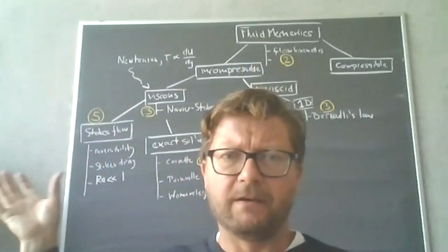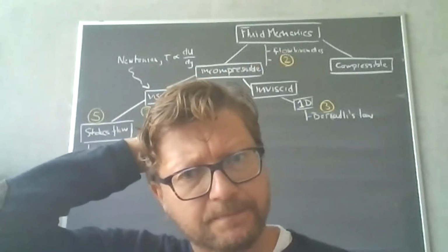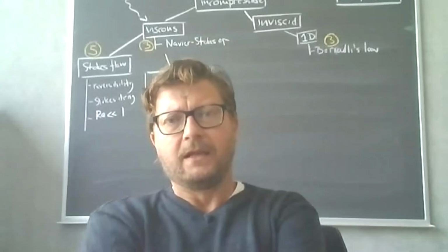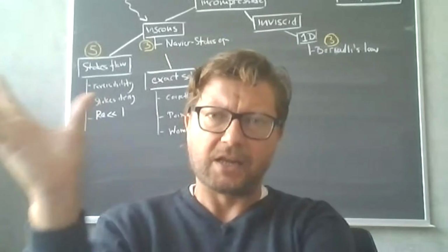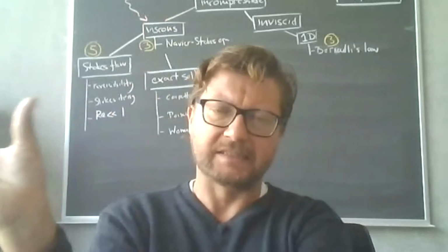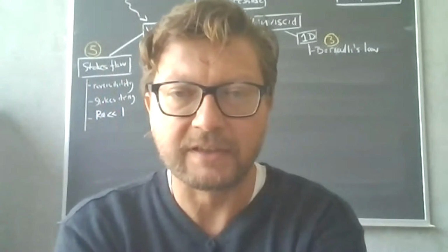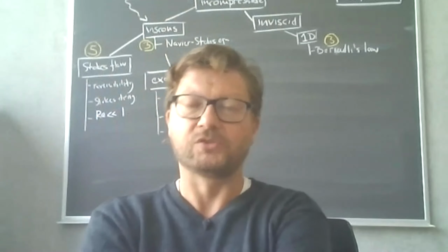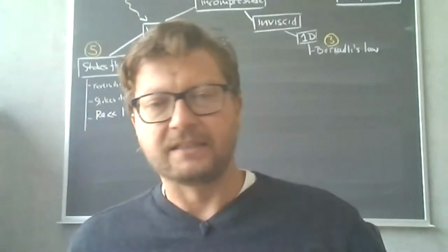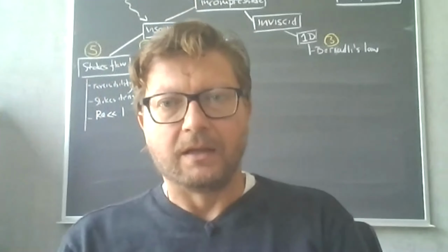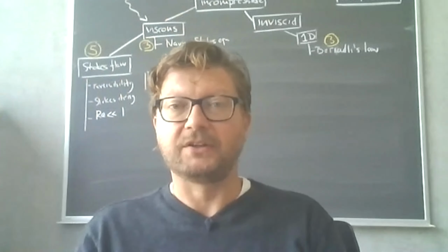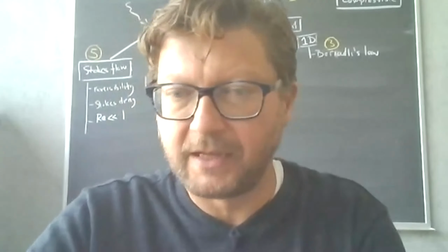So we have one extreme, very, very low Reynolds numbers, which occurs quite often actually in biomedical flow problems. And then we looked at another phenomenon, which was sort of on the opposite side. It was for maybe not very large, but for considerably or moderately large Reynolds numbers. Also very large, but it starts already at Reynolds numbers of, let's say, 10 to 100. We start to get the phenomenon of boundary layers. Let's see what we did here on the boundary layer problem.